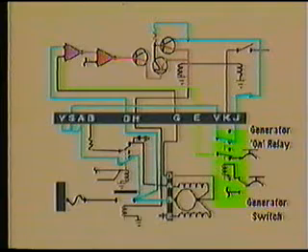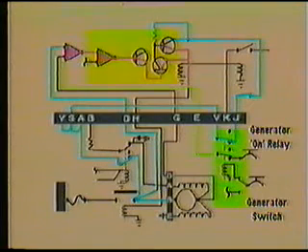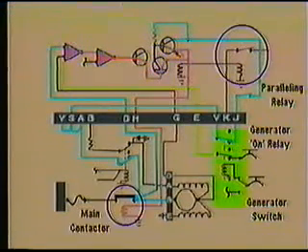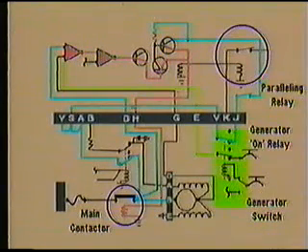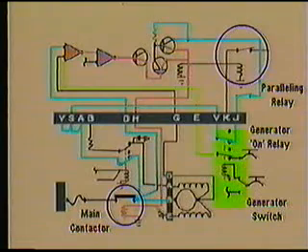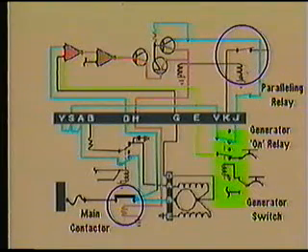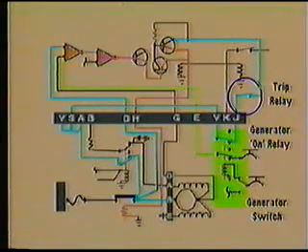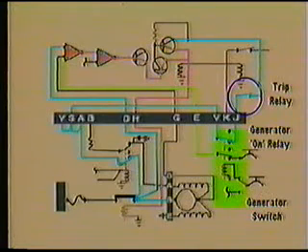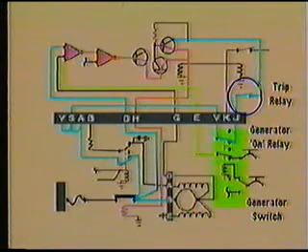This output will also cause a second operational amplifier and several transistors to begin to operate. This entire group may be thought of as a large amplifier circuit. The output of this circuit will provide the power to close the main contactor relay and to close a relay within the control panel that is part of the generator paralleling circuit. Also included in this circuit are the contacts of the trip relay. Other circuitry inside of the control panel controls the operation of this relay.